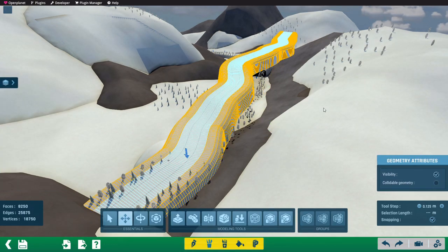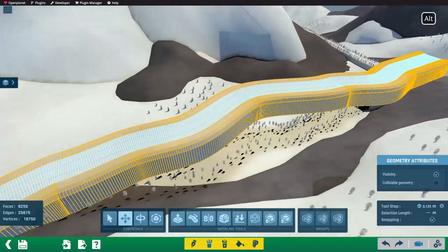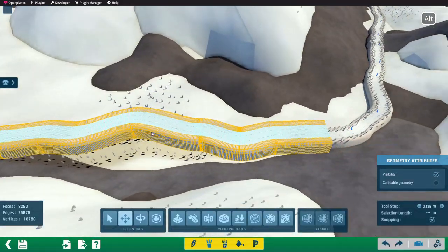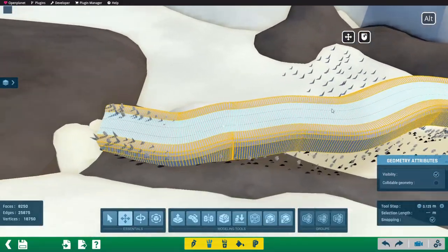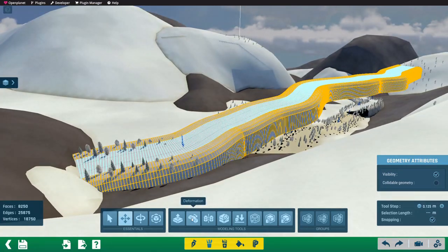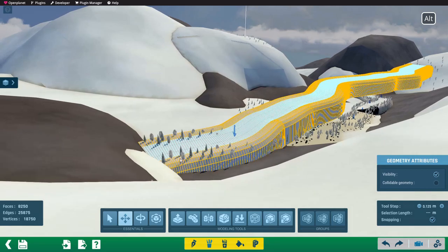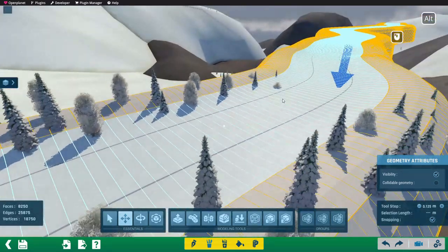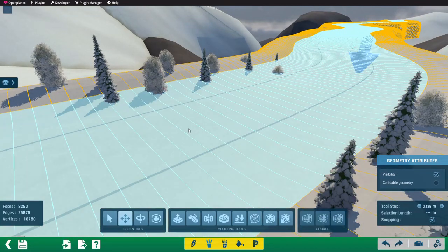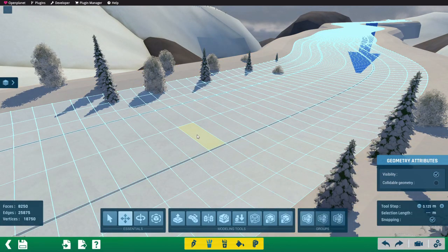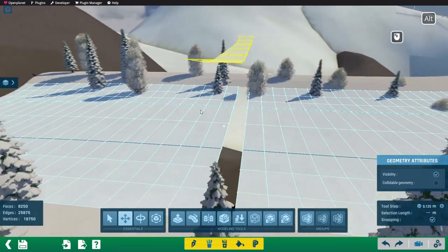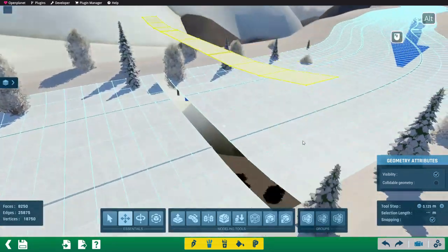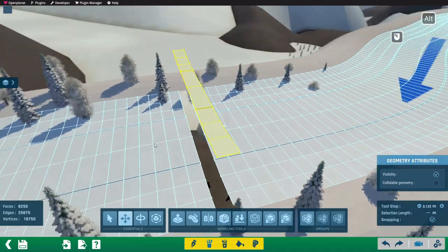For the first deformation I used the geometry internal deformation tool. But one mistake I made was that I applied the initial deformation to a mesh with a length of just one face. The deformation tool places the deformed mesh just in place along the spline, but doesn't connect the meshes. The overlapping vertices just get placed on the same spot, but they do not get united. This means the file size is bigger, which can result in lags in the editor. But it also increases the probability of shadow bugs at each overlap, and can create shadow bug nightmares.